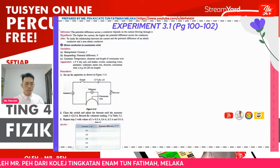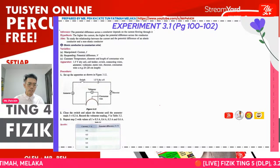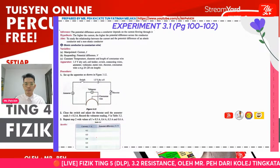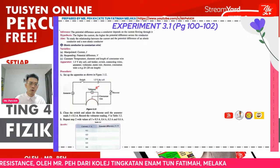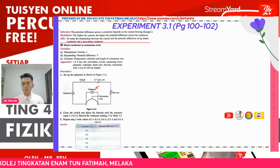The current will be started with 0.2. You can just look at the result table here for the other values. Normally a minimum of 5 readings will be taken. Then we will read the voltmeter reading for the respective value of current.